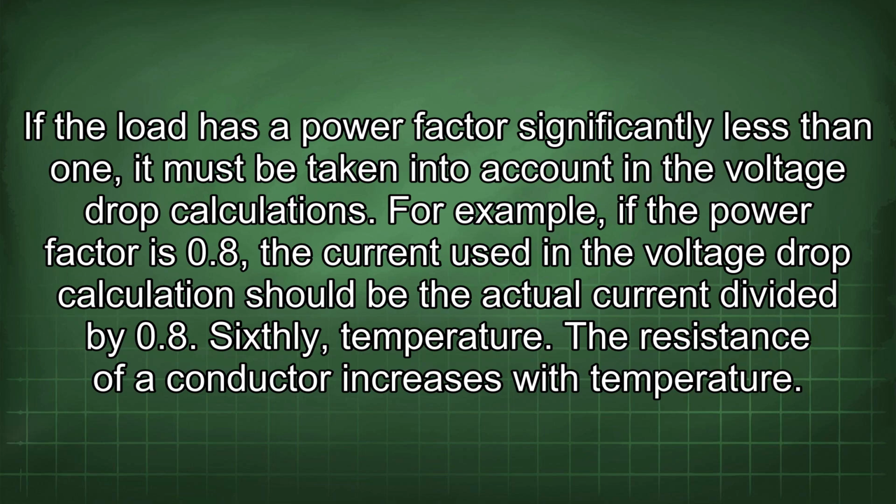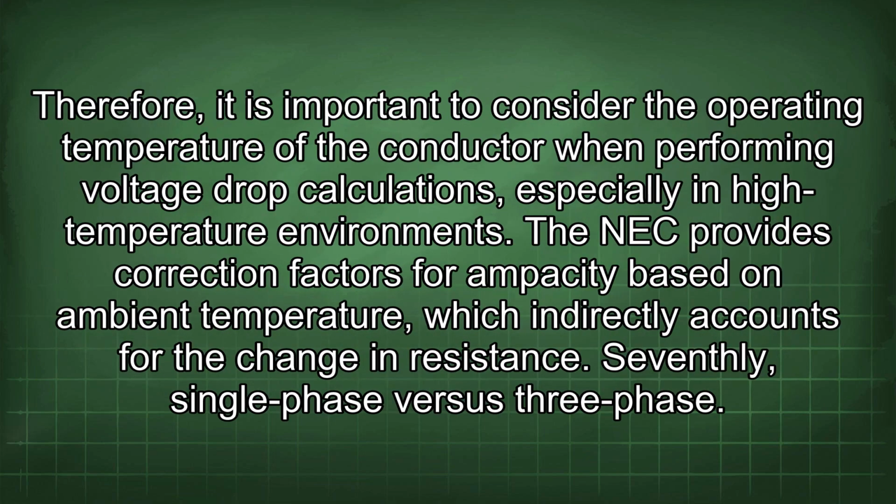Sixthly, temperature. The resistance of a conductor increases with temperature. Therefore, it is important to consider the operating temperature of the conductor when performing voltage drop calculations, especially in high-temperature environments. The NEC provides correction factors for ampacity based on ambient temperature, which indirectly accounts for the change in resistance.